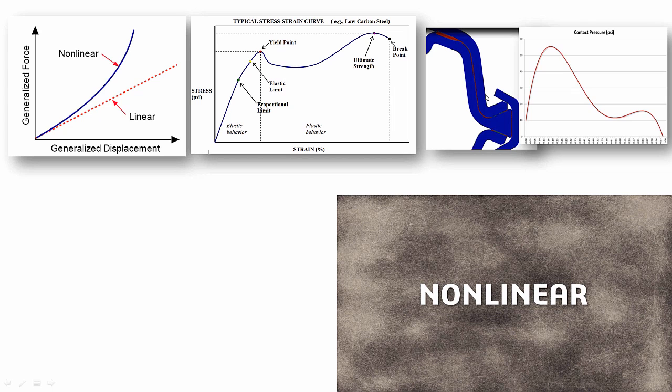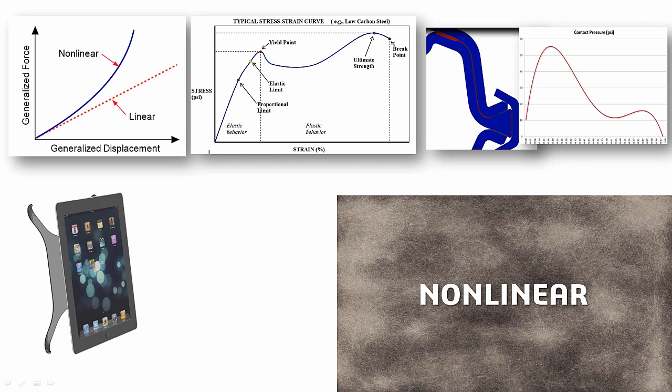The final analysis is contact. Now, contact is really essential because when you take contact between two entities, depending on their elasticity, their point of contact or the area of contact change drastically. That affects the stiffness of the contact interface. So if you want to study a contact analysis accurately, you'll need to run nonlinear analyses.